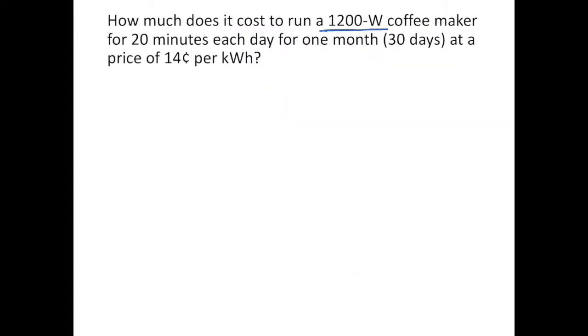All right. Lastly, we get another coffee maker. How much does it cost to run a 1200 watt coffee maker for 20 minutes each day for 1 month, or for 30 days, at a price of 14 cents per kilowatt hour? Actually, in Boston we pay a little bit closer to 14 cents per kilowatt hour, so this will be a good estimate for us. So we have our power equals 1200 watts.